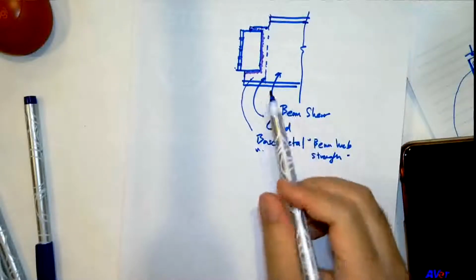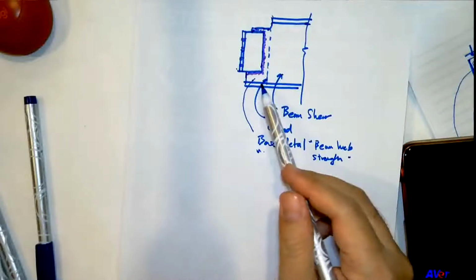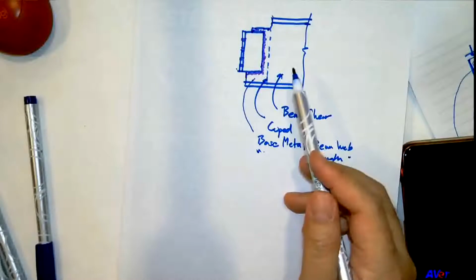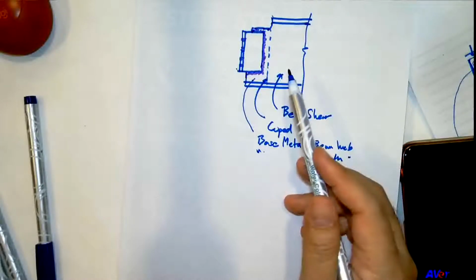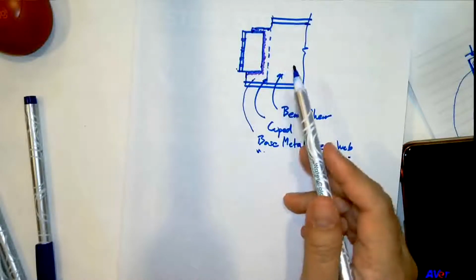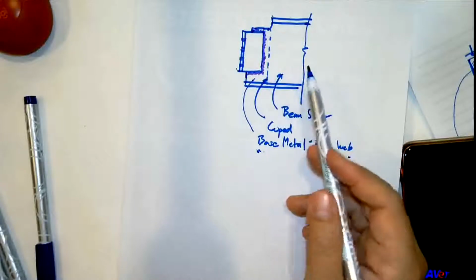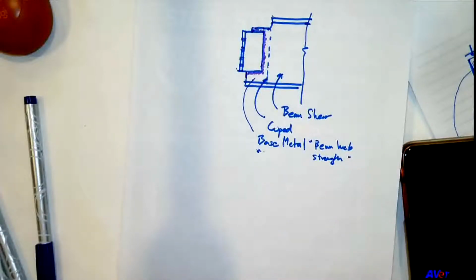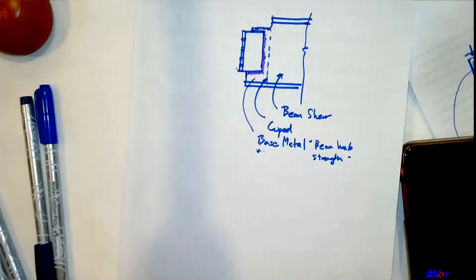Now this again, you have welds on both sides because you have two angles, and you have one beam web which can be very thin, so it can again become the weak spot of our detail. But one thing extra that may occur with this detail is this.